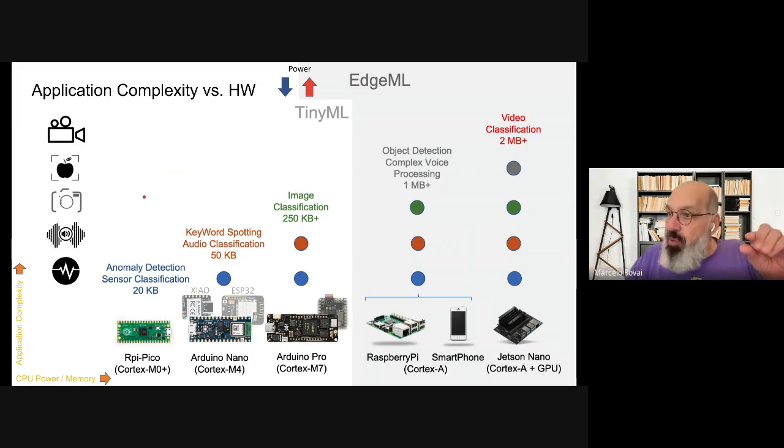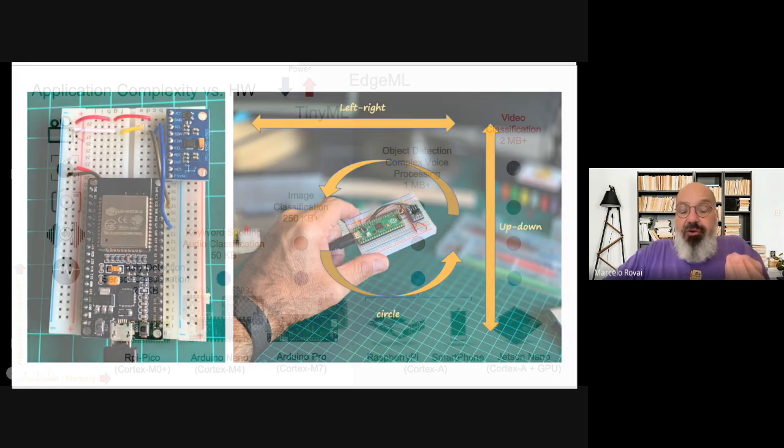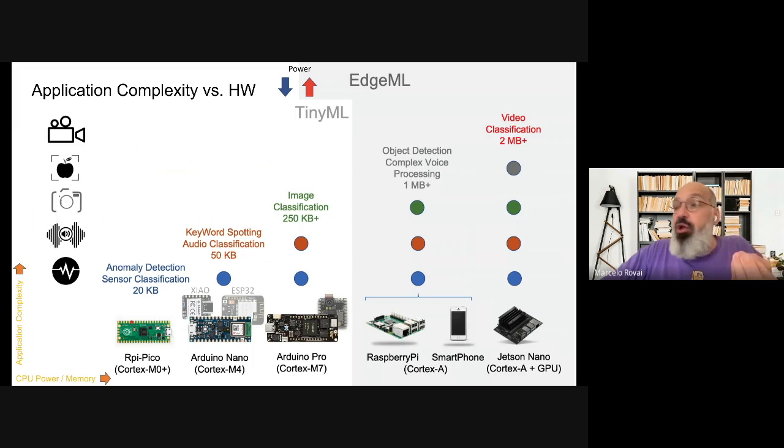So you need a very small model. The memory does not need to be big. I don't need a big processor. So, for example, I can use a Raspberry Pi Pico. It's a $4 PCB. I can connect an external accelerometer, and that's it. Because the model itself is only a few kilobytes.